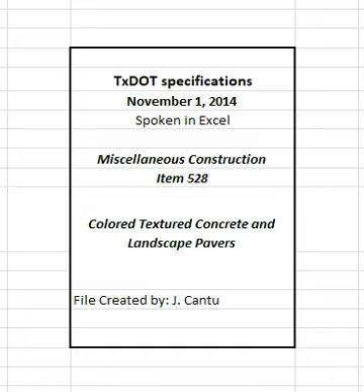3.2.5 Paver compaction. Provide a high-frequency, low-amplitude mechanical flat plate vibrator compactor with a plate area large enough to cover at least 12 paving units and that can deliver a 3,500 to 5,000 pounds centrifugal compaction force. Compact paving units immediately after placement to achieve consolidation of the sand bedding before any traffic is allowed. Bring to design levels and profiles by at least 2 passes of the plate compactor.